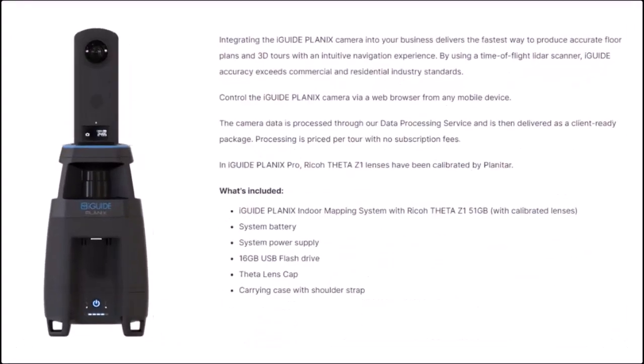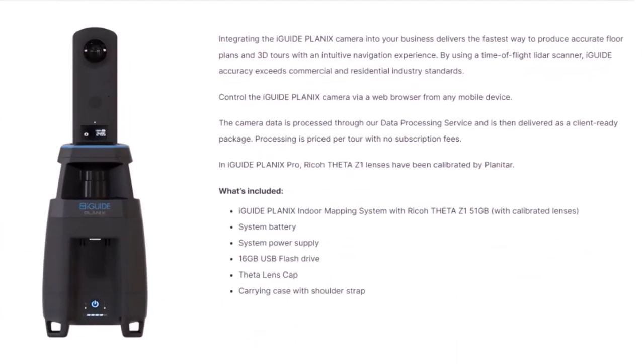The tool I used for the survey was an iGuide camera solution. It cost a fraction of the cost of a LiDAR point cloud solution. We're talking low thousands of pounds here rather than tens of thousands. The tool is static. You mount it on a standard camera tripod, linked to a device by Wi-Fi.